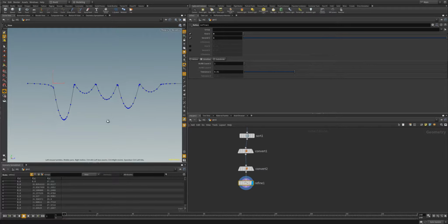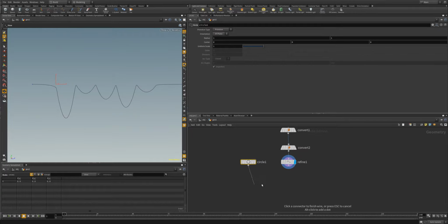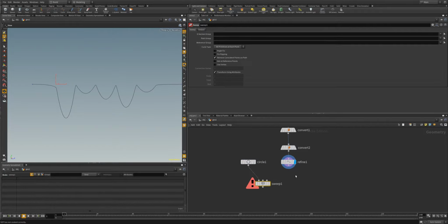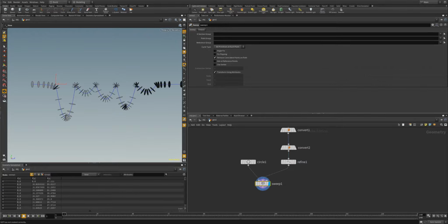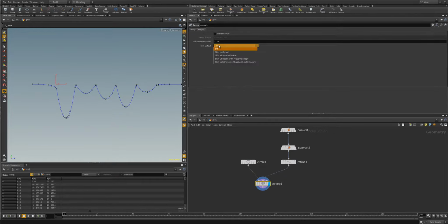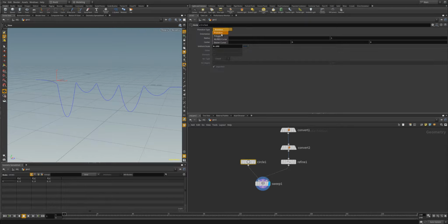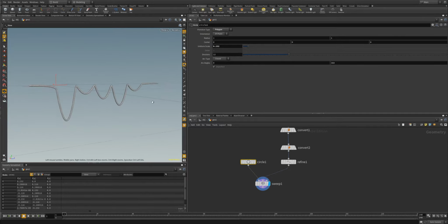That was pretty good. Once we have this smooth interpolation of points on our curve, we can create the outline for our wire, and we'll just go make a sweep, bring this in here, and we'll decrease the scale of our wire. And then once we have our sweep, we'll just output and skin this with preserve shape. Oh, it disappeared. Oh, it is because I'm using a primitive and I should be using a polygon. There we go. And there we go. We've got some nice hanging wires.